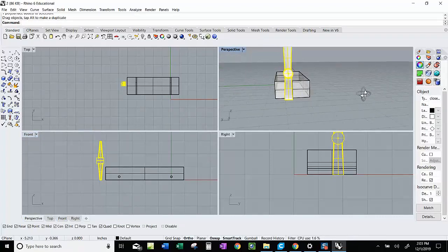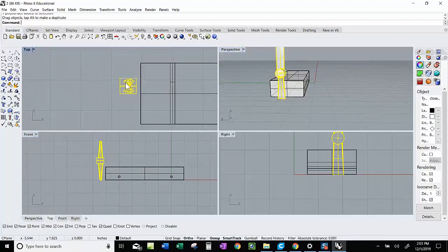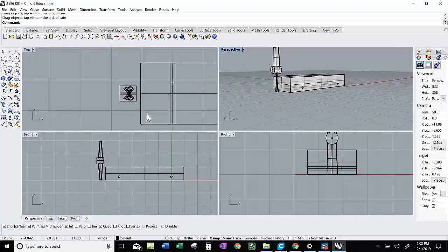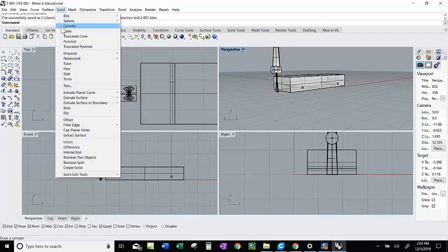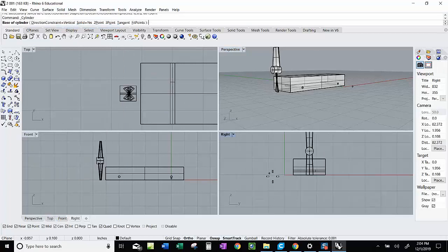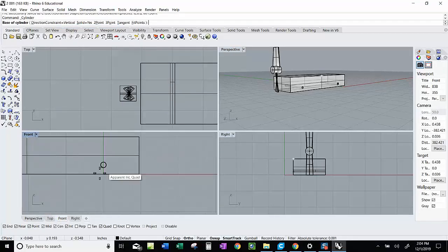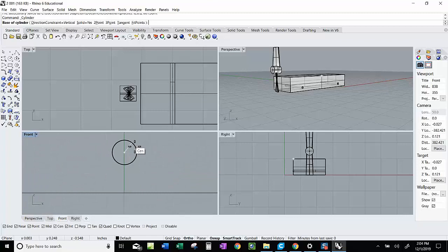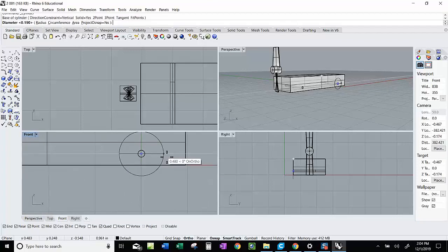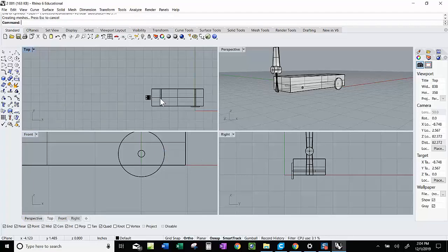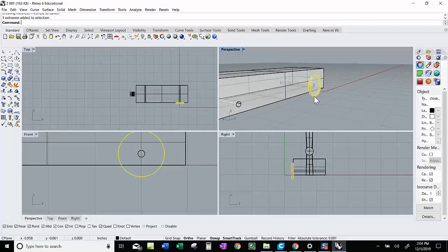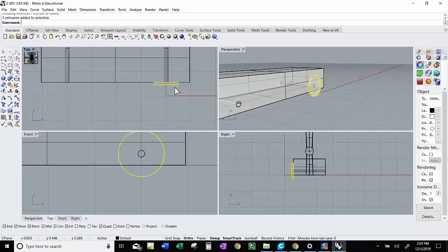All right. Next thing to do is the wheels. By the way, there's a way to get this perfectly aligned. So the wheels have to be 1 inch in diameter and 1 inch thick. I'll do an incremental save. And I'll make the wheels from this perspective. Might as well just make it lining up with the holes. So 1 enter and 0.1 for thickness. That's what I have now. Move it out a little bit.